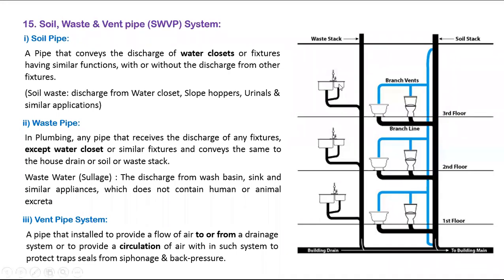So that's why you have to provide one vent down here. If you are providing the vent, while the water goes from up to down, it will go freely. Otherwise the water will get cyclonic action and the flow will be affected. So that's why we are providing one vent pipe here, vent everywhere. Vertical lines we are making vent. For the main stack and separately for every stack we are giving intermediate vent also. Double piping system we can see in the venting system.